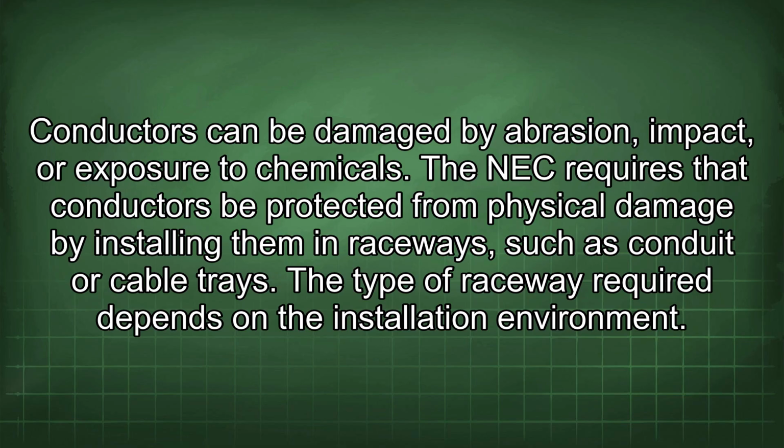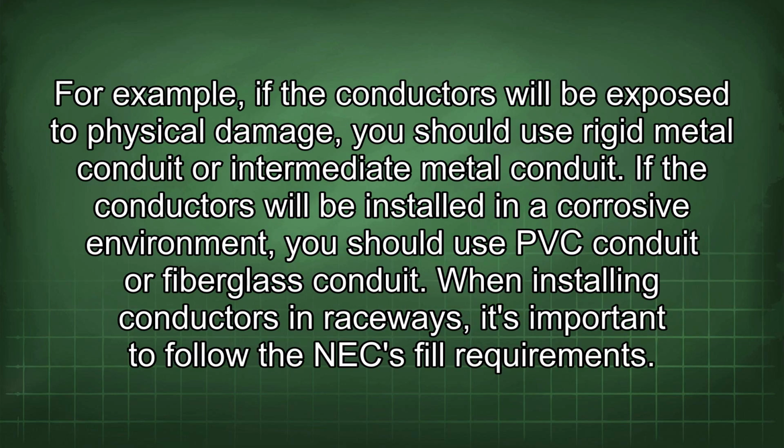The NEC requires that conductors be protected from physical damage by installing them in raceways, such as conduit or cable trays. The type of raceway required depends on the installation environment. For example, if the conductors will be exposed to physical damage, you should use rigid metal conduit or intermediate metal conduit. If the conductors will be installed in a corrosive environment, you should use PVC conduit or fiberglass conduit.